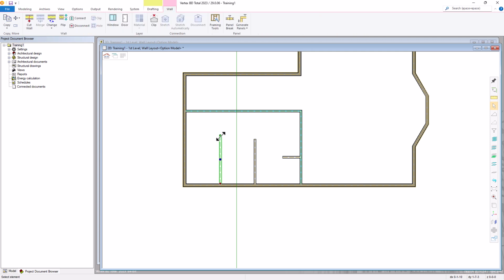If you select the wall and right click on the dot, you'll see we have several more editing tools. We have the move wall end, which is the same as just selecting the endpoint of a wall and stretching it or moving it up. We have move wall end with reference point. Basically, it's similar. You select the wall, select, let's say, a distance that you know, a reference point. You pick this point and then the next point, and whatever that length is, let's just say that was 3 feet, then this wall would extend up 3 feet.